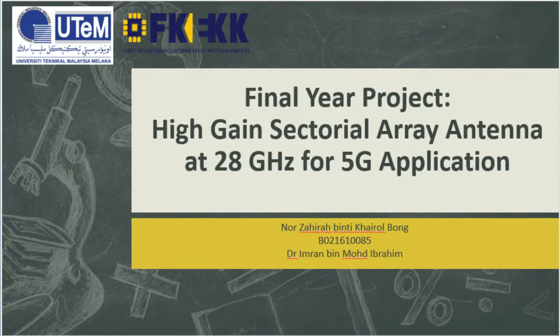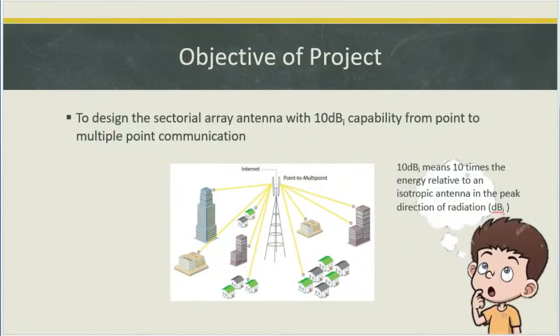I am Nor Zahirah binti Khairol Bong, presenting my video demonstration on my final year project entitled High Gain Sectorial Array Antenna at 28 GHz for 5G application. So let's proceed. First of all, the objective of my research is to design the sectorial array antenna with 10 dBi capability for point to multipoint communication, designing the sectorial array antenna to have a high gain which can reach 10 dB, with a return loss of not less than negative 10 dB as the limitation for this research.